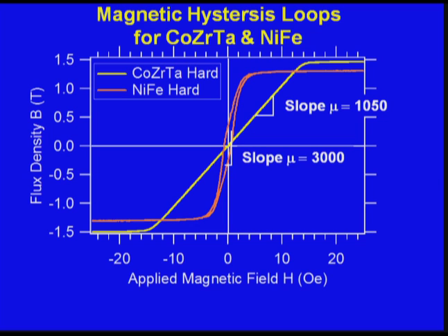The other parameter that's important to pay attention to is, if you remember in the loss components for the inductor, the third term was hysteretic losses. Well, that's what's happening right here. You have an opening here, and what happens is that you're going in one direction and then you switch in the other direction. There's a period of time where the permeability is something on the order of 1 or something smaller than the permeability of the device as it switches over from this side of the loop to this side of the loop. So you have these minor loops basically going on. And so that means that your inductor does not have as much inductance as you want it to, and then you end up having some losses.